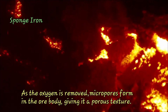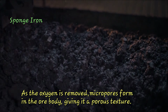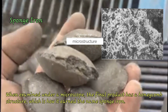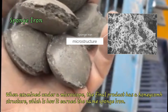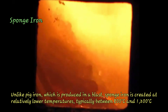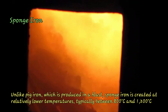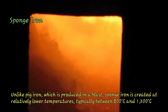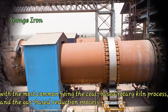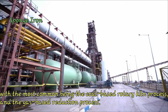As the oxygen is removed, micropores form in the ore body, giving it a porous texture. When examined under a microscope, the final product has a honeycomb structure, which is how it earned the name sponge iron. Unlike pig iron, which is produced in a blast furnace, sponge iron is created at relatively lower temperatures, typically between 800 degrees Celsius and 1200 degrees Celsius. There are various methods for producing sponge iron, with the most common being the coal-based rotary kiln process and the gas-based reduction process.